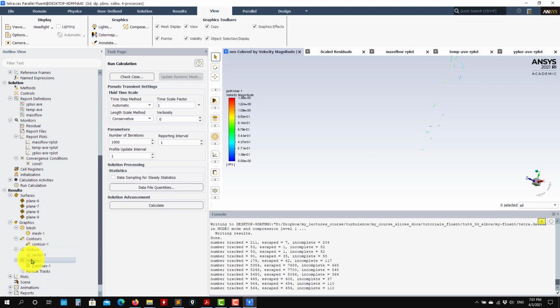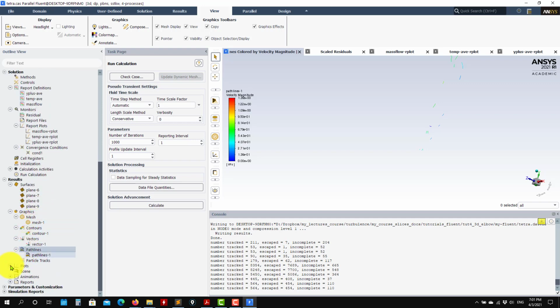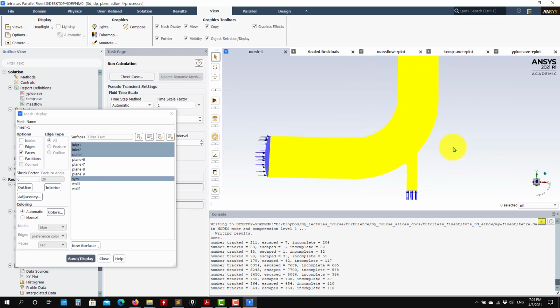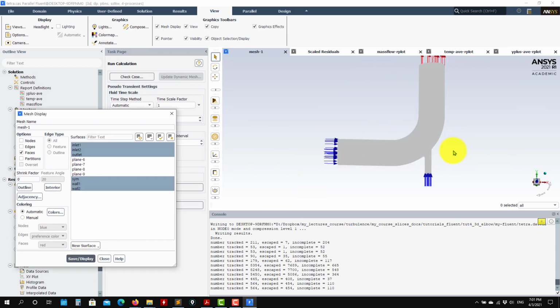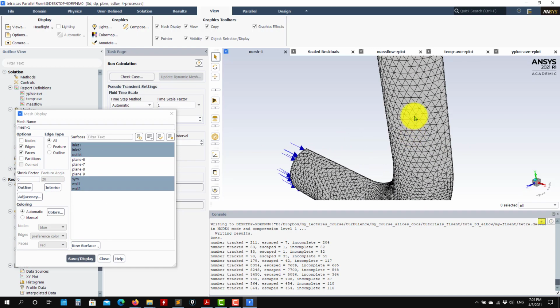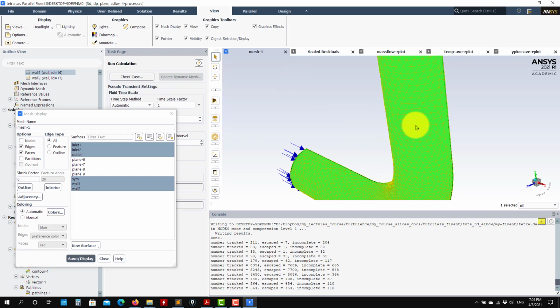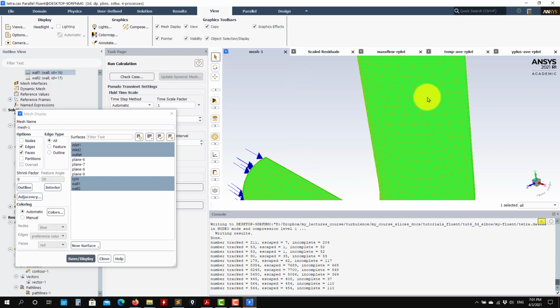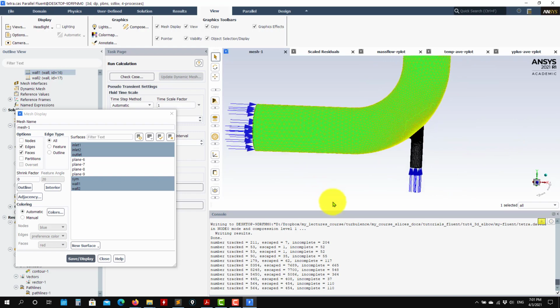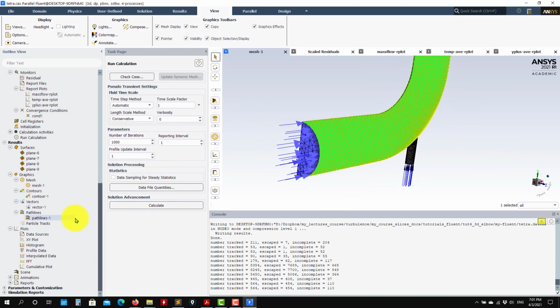Particle trace is something similar to path lines, but here you are adding mass to those particles. So for the moment, we don't need to do that. So what else? You can also do the plots along lines. So if you want to do the plot of u plus versus y plus, what you need to do in this case is just pick a location in the domain. For instance, you want to do it here, sample wall shear stress there, then align normal to the wall, get the velocity and do your plot. Okay, so you can do it anywhere. Nothing changed. All that sampling is the same.